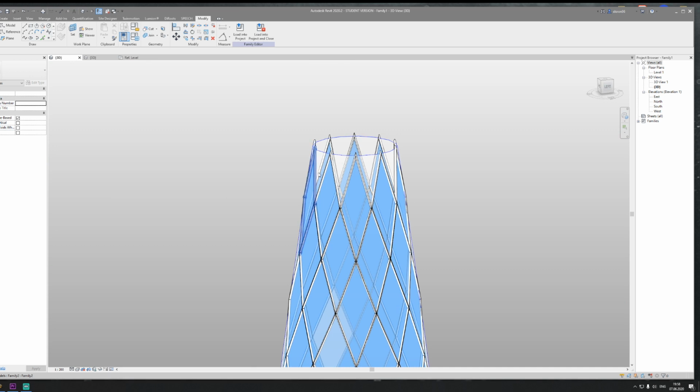But what about that thing? Yeah, this is a problem. You cannot do anything with that because Revit cannot split it. Because you have only 3 points, but Dynamo needs 4 points here.